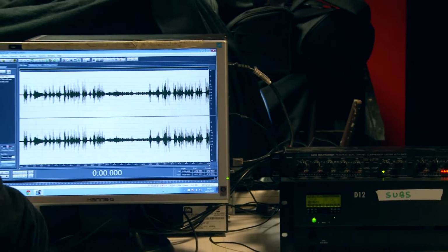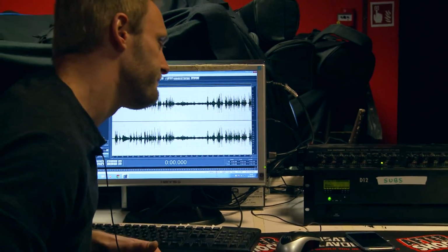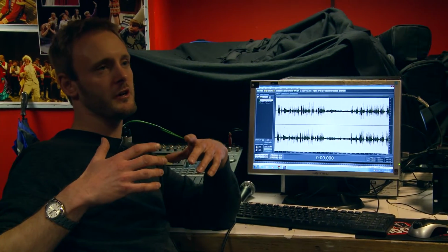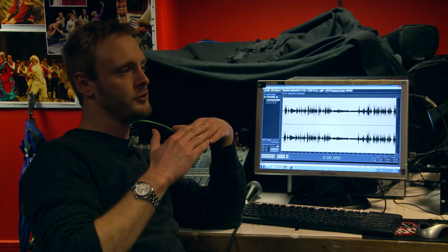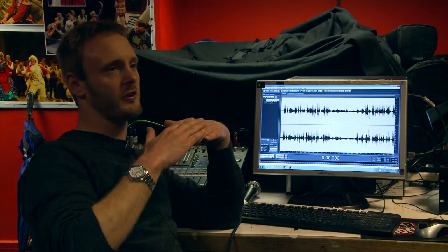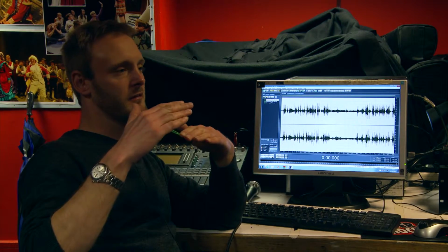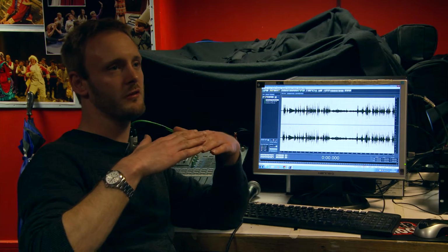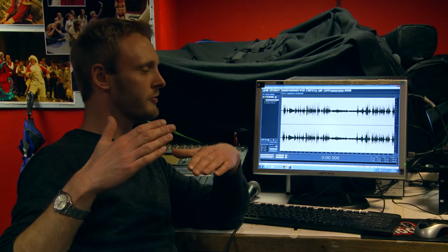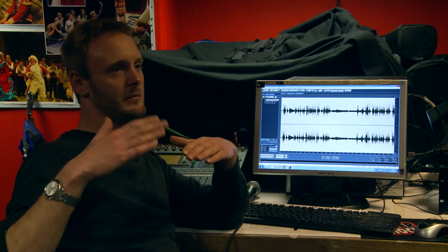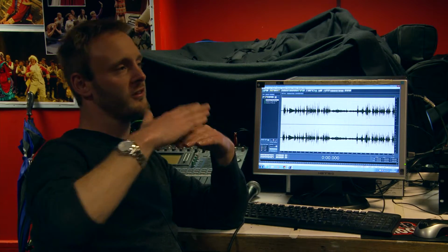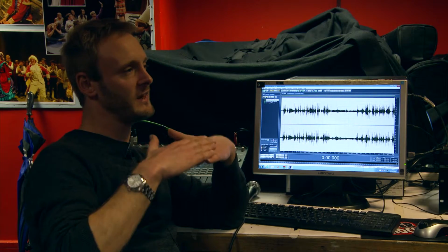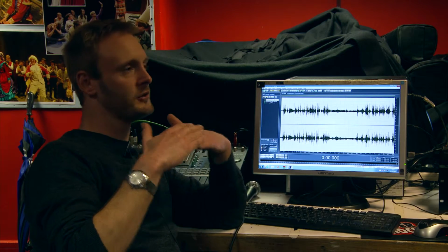There's a lot more to it than that, but the reasons we use compression in a limiter format with a high ratio: if you're approaching the point where your digital system is going to top out, you've run out of data, you're going to hit digital noise. You're going too hot to tape, or too hot to track. By setting it as a limiter, it won't exceed that -20 decibel, or whatever you set the threshold to. And that's really good for protecting your recording inputs.